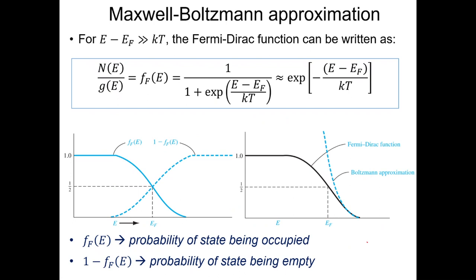Now, often in further derivations, you will come across an approximation called the Maxwell-Boltzmann approximation, used for simplifying the Fermi-Dirac distribution, because often we may be dealing with this tail, which is the region where the highest number of electrons are present. As you remember, as you progress in energy level, the density of states will increase. So this tail talks about the region which will have most of the electrons, so we may often simplify things for easy mathematics.